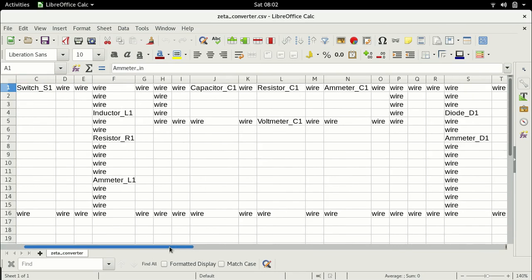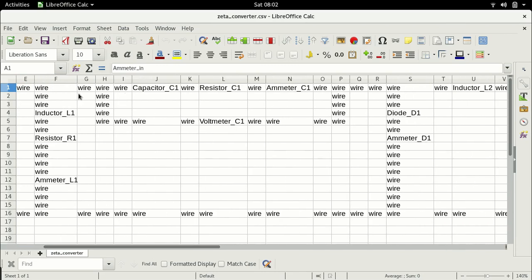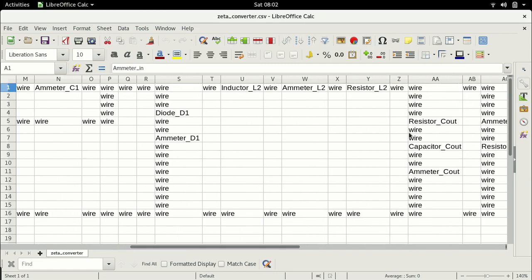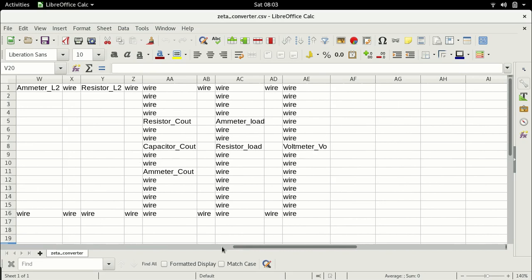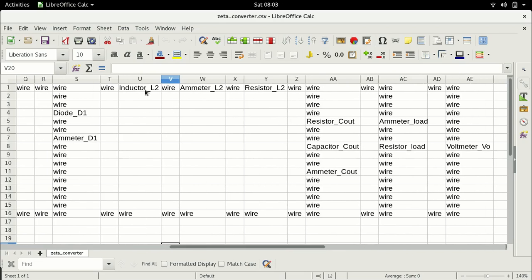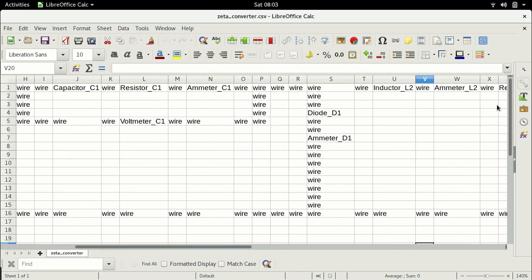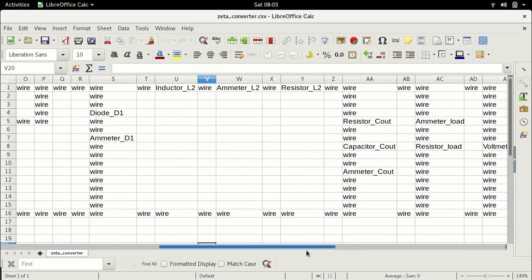Now, about the forward path, initially the capacitor is uncharged. So when the switch is turned on, the voltage is zero. The same goes for the output voltage. Voltage is zero. Which means the entire input voltage falls across this inductor L2. So the voltage across inductor L2 is also equal to the input voltage, right? It seems strange, but both the inductors have the same voltage, right?